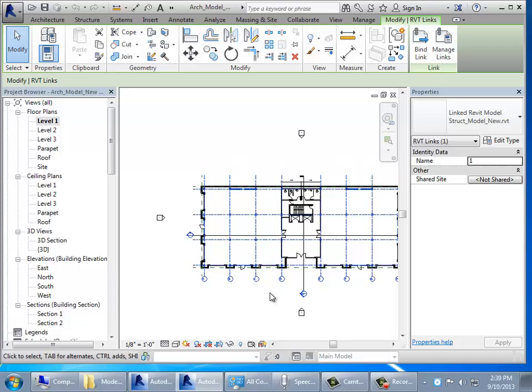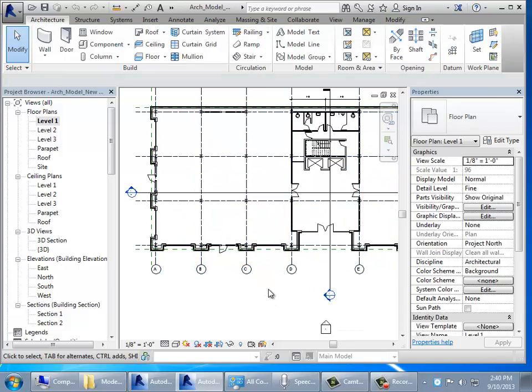So, if you go to the floor plan view of any of the different levels, one thing you'll notice is that using all of these different models really helps a lot with grid lines. Before you do anything in terms of modeling your overall structure, before you put a whole lot of walls and architectural elements in your model, one of the first things I really advocate doing is putting down the grid lines, basically a horizontal and vertical grid, and using it as a point of reference to hang the entire project off of. Whenever you can, measure things relative to those grid lines.